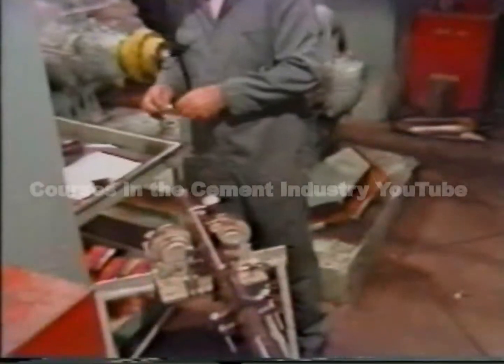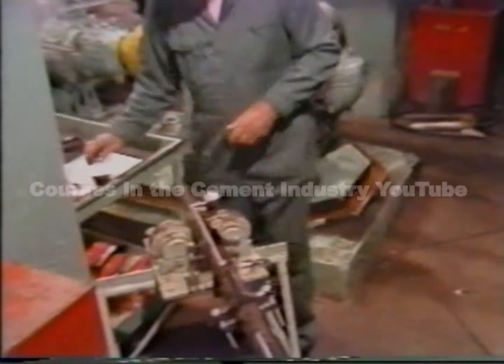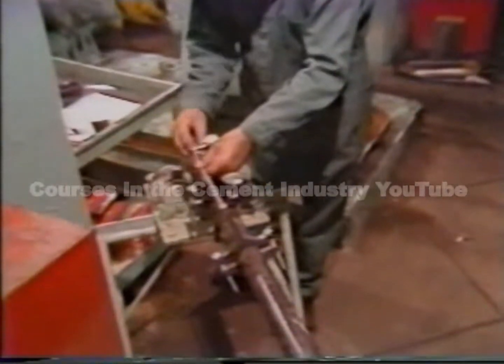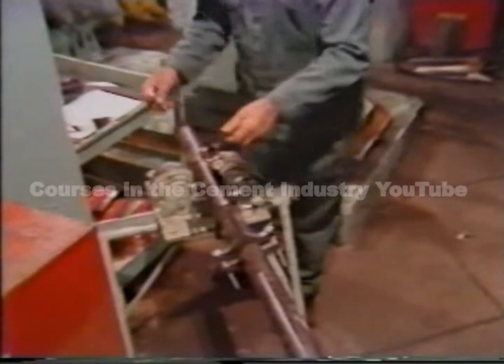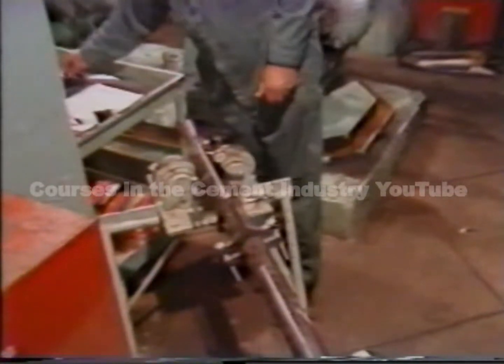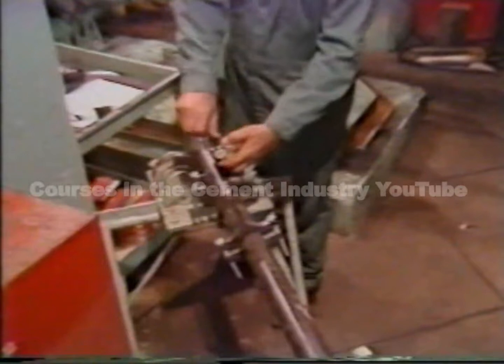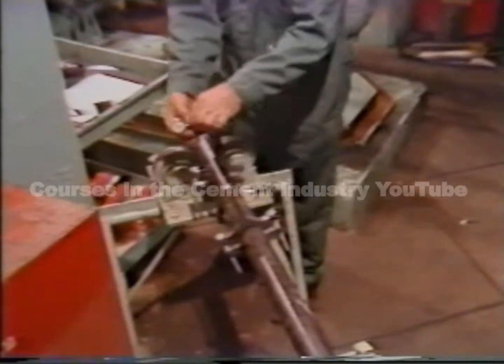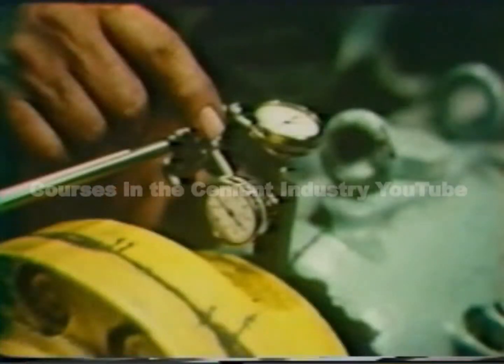When we left the job, the technician had just completed a sag check on his mounting brackets. Remember, the amount of rod sag must be considered when taking the top to bottom parallel alignment reading. You'll see that in detail later on. Right now it's time to install the dial indicators on the pump and motor shafts.